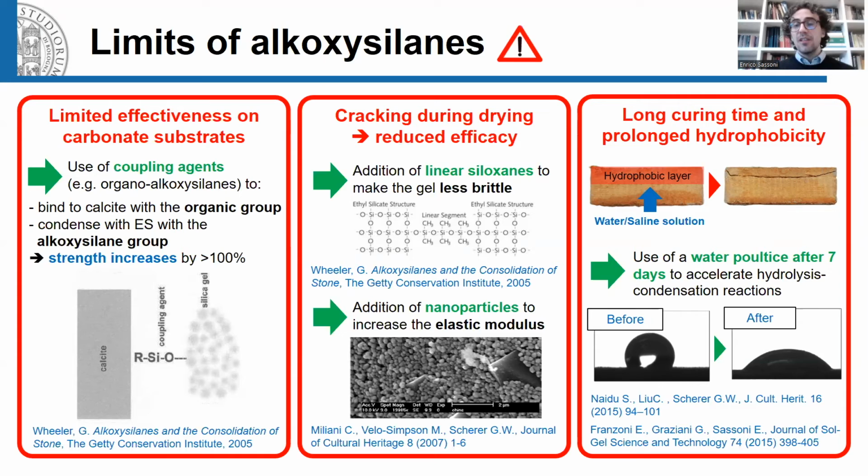Another known limitation or delicate aspect of alkoxysilanes is that they make the treated stone hydrophobic for a very long time, more than 6 months in the field. This can be an issue in case water or saline solutions are present behind the hydrophobic layer, because this could lead to the detachment of the treated layer and so the failure of the intervention.